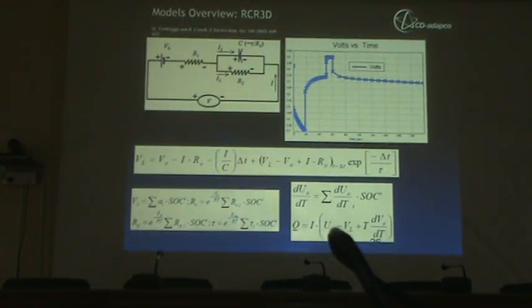Coming to the RCR model, as I talked about previously, it is a regression-based model. You can add as many circuits as you want. The more circuits you add, the more the number of parameters you have to regress. There are a few regression models already available in Battery Design Studio. You try to get the data from a supplier or from your lab, and you try to regress, say, a 2 RC circuit for that particular data. So you have to find all the different parameters involved.